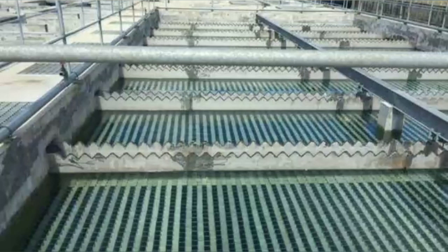Just like we took up one extra component, that is, plates inside the tank in the case of plate settlers, here now we are providing a series of tubes or multiple tubular channels which are sloped at around 60 degrees in order to enhance the settling rate. And these tubes are provided adjacent to each other. This entire mechanism is done inside a tank, and these are more effective when we compare to the plate settlers, since this provides for a particle a settling depth that is significantly less than the settling depth in the conventional clarifiers, and also it reduces the settling time.